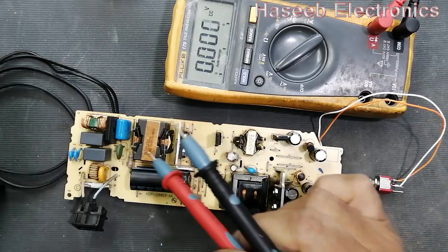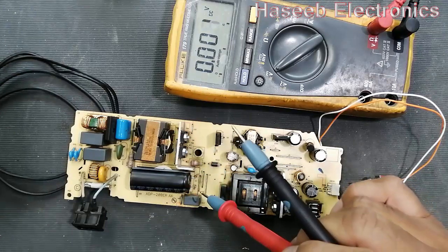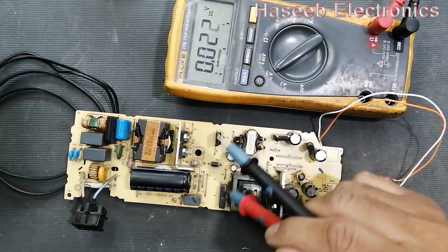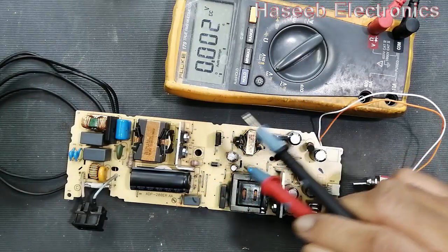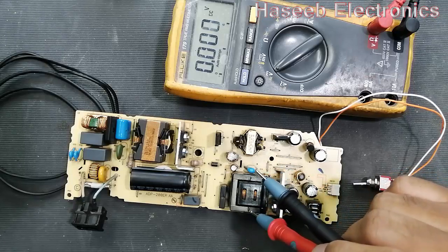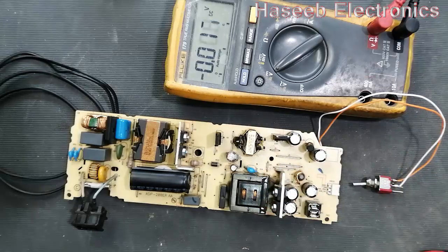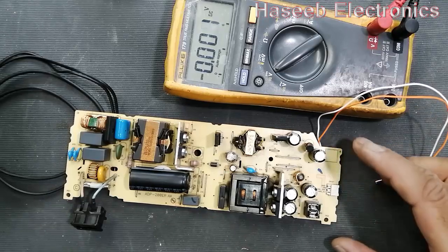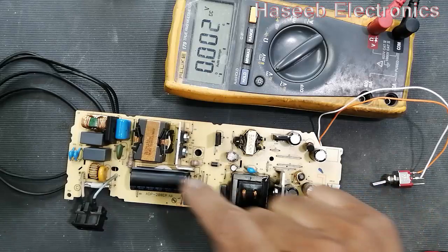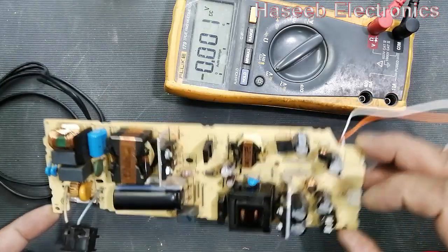So this circuit is responsible for maintaining the DC voltage level at 410 volts, because the supply needs 410 volts to work properly, to give a proper output without any drop, without any load effect, to maintain the load regulation and the line regulation. So it needs 410 volt to turn on. So let's see how it will boost the voltage.